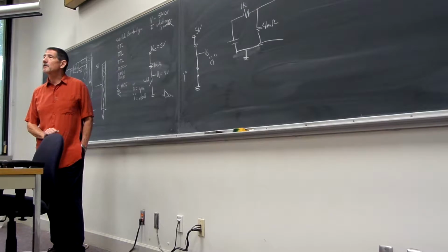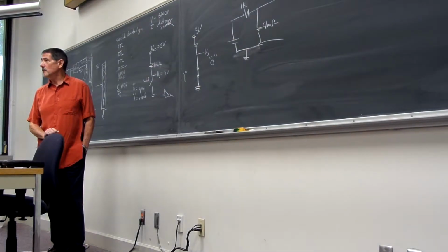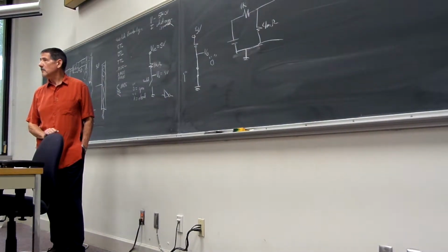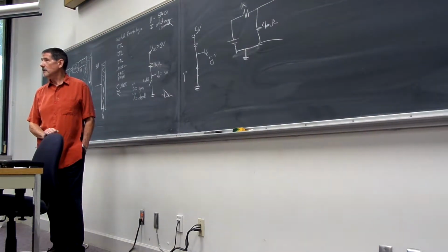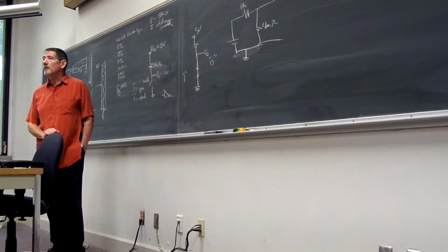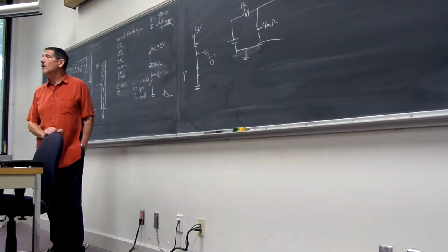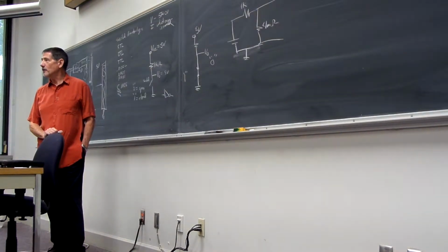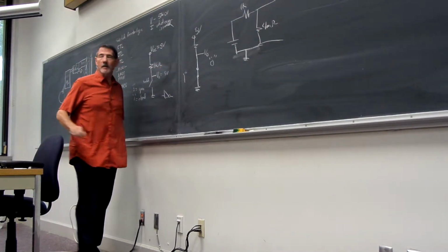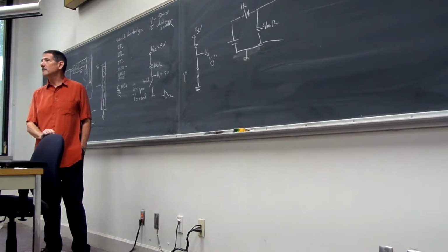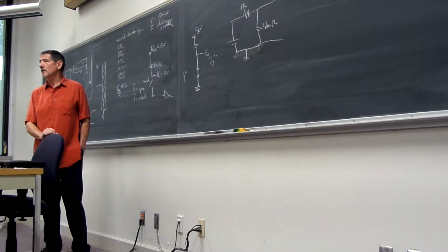Now, what happens if the switch has a resistance of a kiloohm? Good or bad? Bad, because when the switch is now closed, what are you going to get out? 2.5 volts. Is that very good for a logic system? No. What would happen if the switch had 400 ohms? Still not very good. What if instead of making that 1K, I made it 10K? Would a 400 ohm switch resistance hurt me much? Not as much.